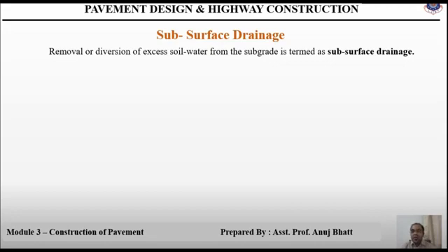Now the subgrade drainage or subsurface drainage is necessary when the road is in cutting and water is seeping from the sides, at that moment you need to provide the subsurface drainage. Also, when the road is near the foot of a hill and is likely to be damaged by water flowing down the hill, at that moment subsurface drainage is a must.